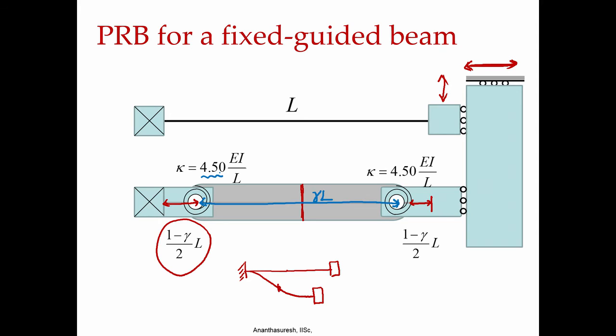and the kappa here turns out to be 2.25 is what we had. Now, it becomes 4.5 for either of those, because they share the load in a way, because when you break it here there is a force coming on both of them. So, it becomes twice of what we had earlier, because this is like two springs in series where the spring constant becomes half, that becomes 2.25 eventually, but both places we have a torsion spring, that is over here as well as here.